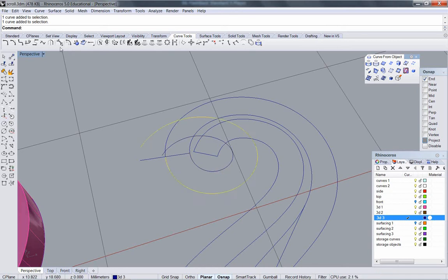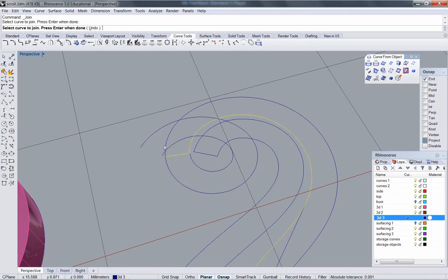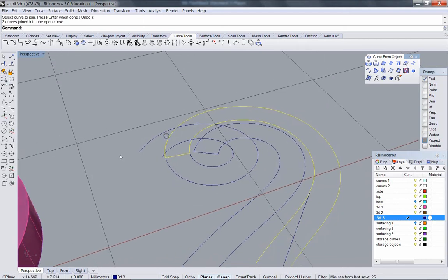Going to go ahead and fillet the edge so it matches. I'm going to copy this with Control-C to my Windows clipboard. I'm going to join this, this, and this. I'm going to Control-V, put that copy of the curve back in, join it to this and this. I'm going to put my end lines in place.